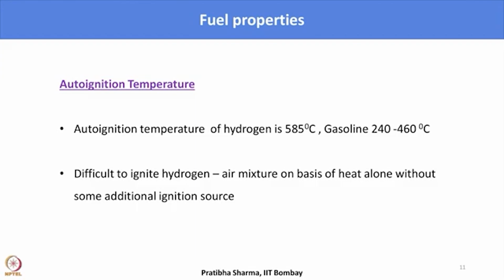But at the same time, even on higher compressions, the ignition will not take place on its own. So an external ignition source or a spark is required. So ideally it will be a fuel for a spark ignition engine.